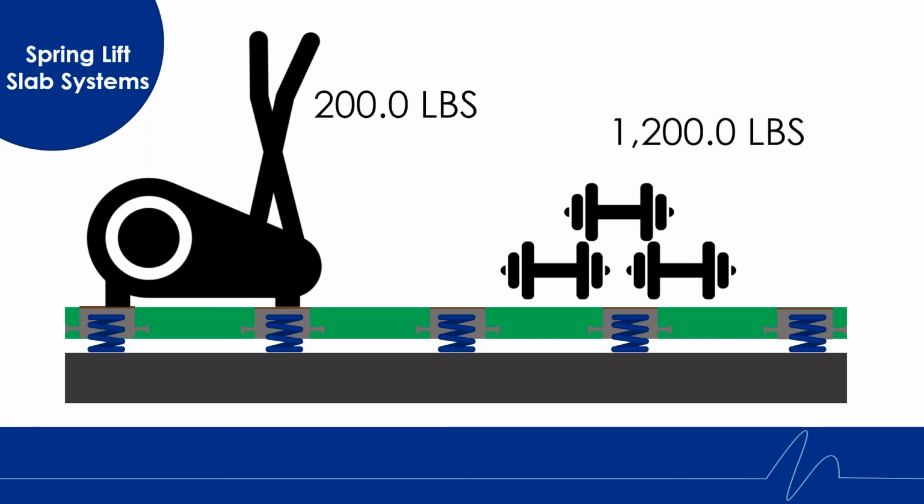How Kinetics has chosen to approach these situations is by zone loading. Normally, there are fitness equipments that require electricity, so the outlets are not going to change locations. So we know those machines that require electricity will be closely located to those outlets. So we designate a certain square foot to accommodate those common weights, so that when you change a 400-pound treadmill with a 300-pound elliptical, that weight is not drastically different. Thus, the springs will be able to accommodate that change.